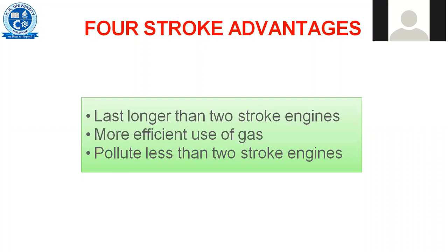Instead of pressure difference just going on. The moment the exhaust valve opens, because the pressure inside the cylinder is always higher and outside is lower, the gas escapes. Whatever little is left over inside the cylinder also gets out of the cylinder by the upward moving piston. That means this is evacuating all the gases which are there inside. Maybe small traces may be present, but that's insignificant.